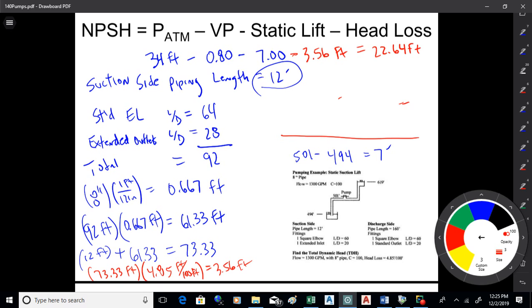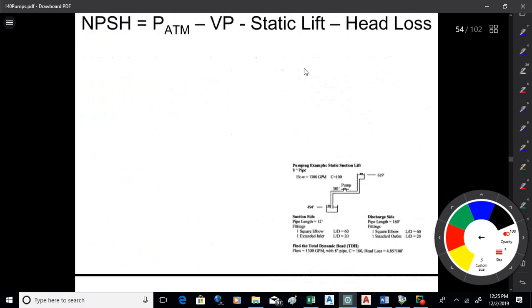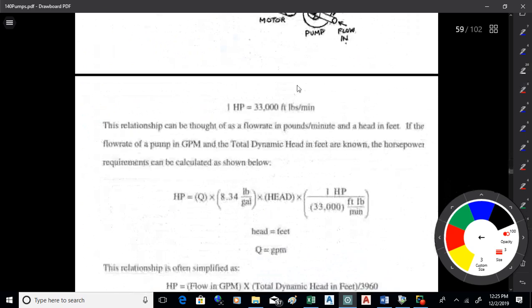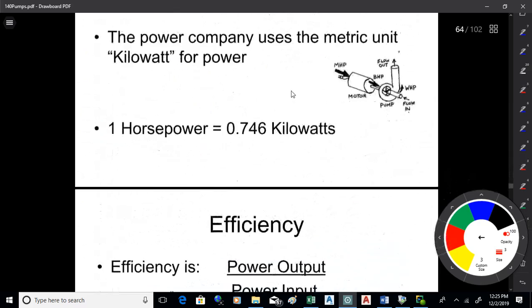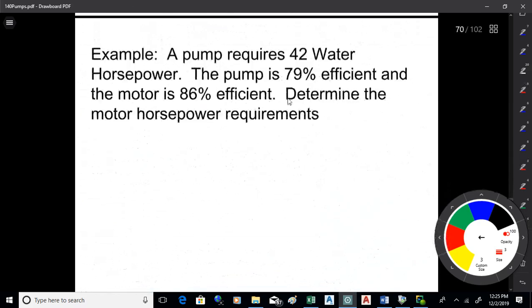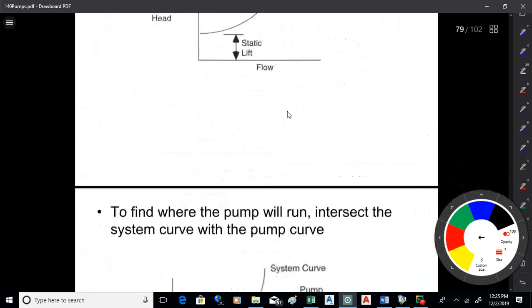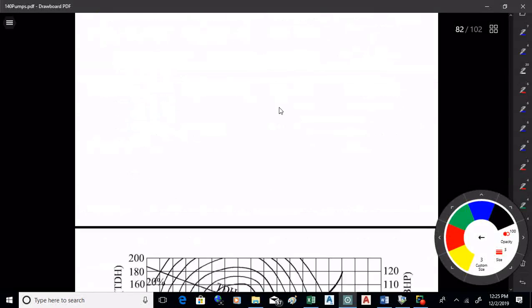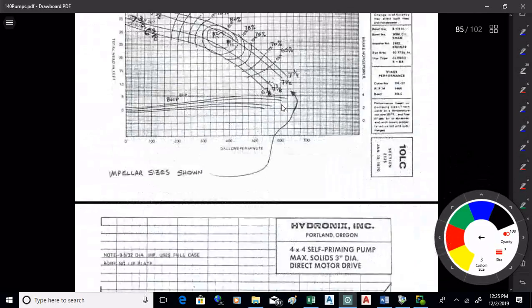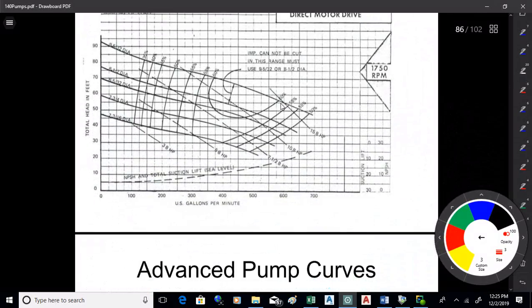What page is that again? 153. If you look on that pump curve on the lower right-hand side, you'll see an NPSH column there. Okay. And that's telling you, for these different conditions where you might be pumping, you need this much energy for the pump to function properly. Okay, and we'll get to that here in a bit, okay?